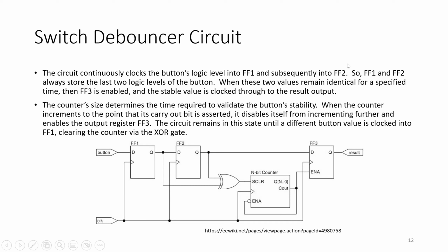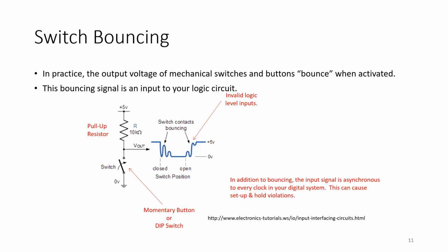Yes, sir. Can you go back to where it looks like the signal is bouncing up and down? That graph. So are we setting the timer for that long amount, or is it like the first bounce? Are we tuning it for the first bounce? No, for the 10 millisecond is from this point to here, and even a little bit further. Okay, so we're just accounting for the variations in between that. Yeah. Okay.